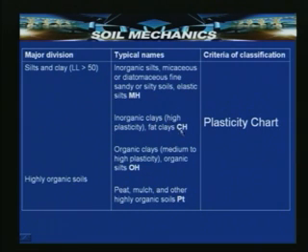Inorganic clays of high plasticity, also called fat clays, are CH. Organic clays of medium to high plasticity, organic silts, are OH. So, if the liquid limit is greater than 50, then they are divided into MH, CH and OH subgroups, with different soil classification symbols.